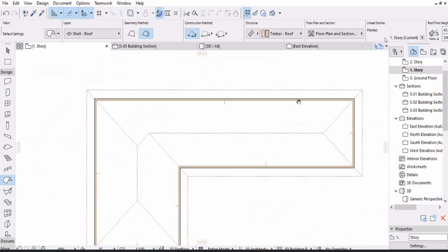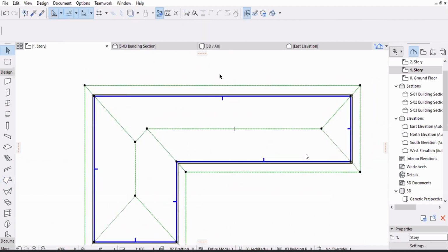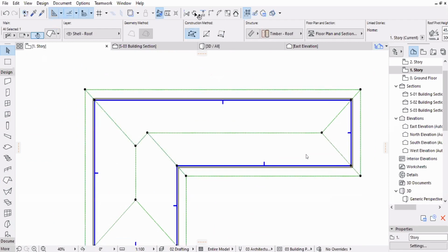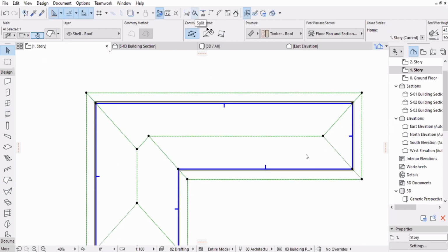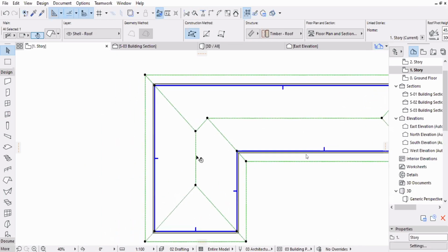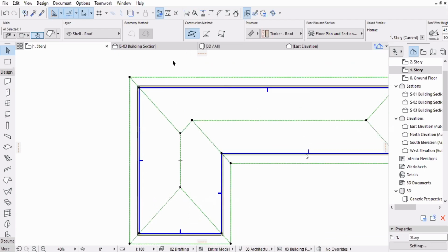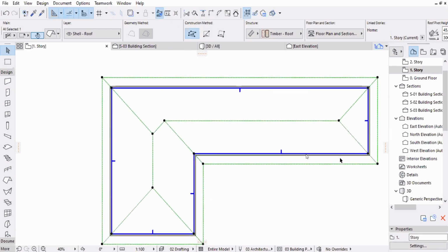So you want to modify this. The simplest way to cut this roof here is using a command called split. That will take care of this part of the roof. But if I want to do a little skylight here, then I can't use any of these editing tools. I need tools specific to roofs. You can use a combination of tools essentially.